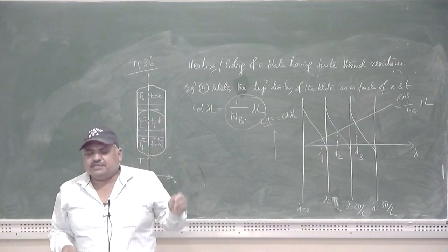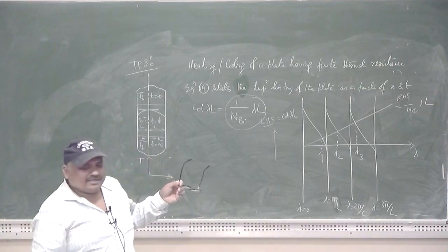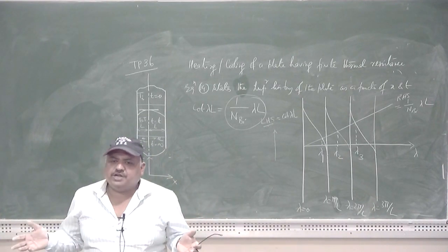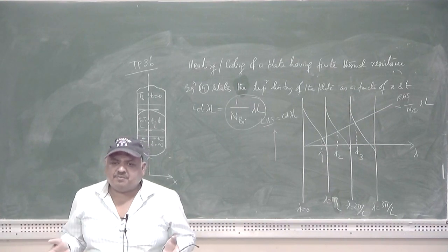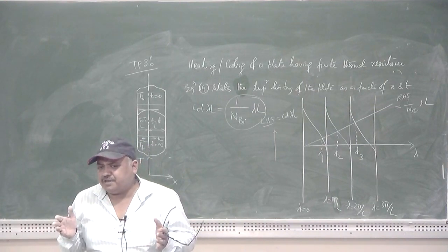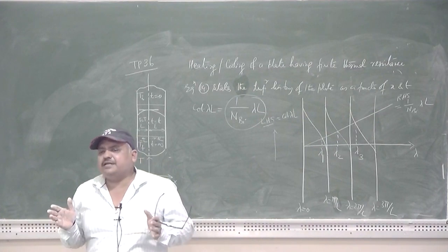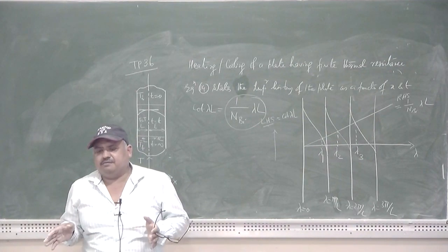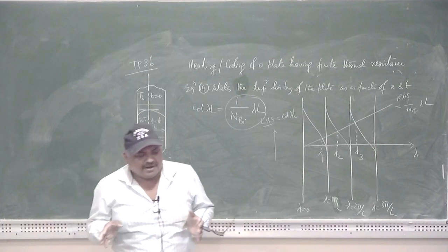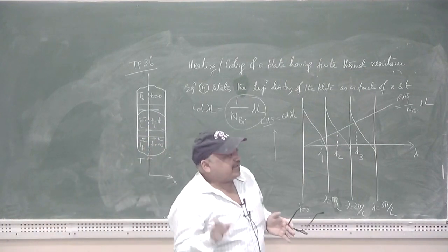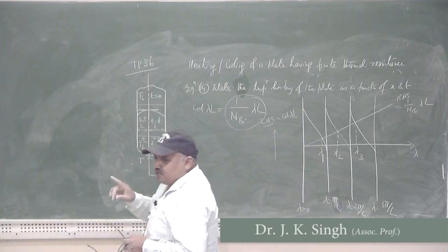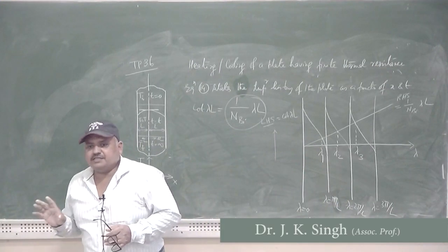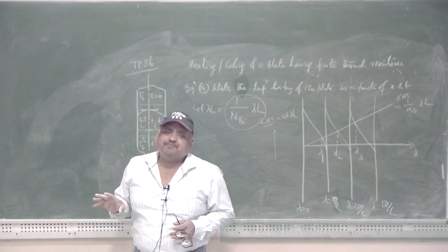I will try to provide you some ideas regarding the utility of the Heisler diagram, how this diagram can be made, and how the temperature of the quenching plate can be determined if the Heisler chart is available with you. This concept will be of immense importance for one of the labs of your transport phenomena course, the cooling of ingot. In the cooling of ingot experiment, by taking the metallic ingot, you have to evaluate the convective heat transfer coefficient on the surface and the thermal conductivity of the material.